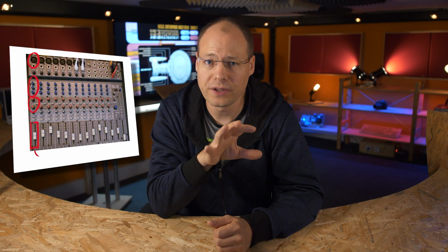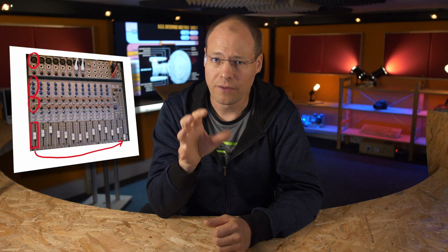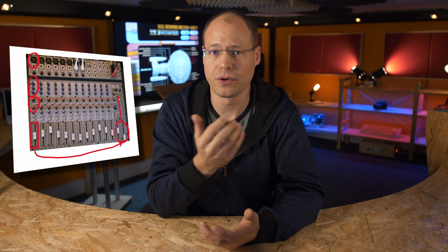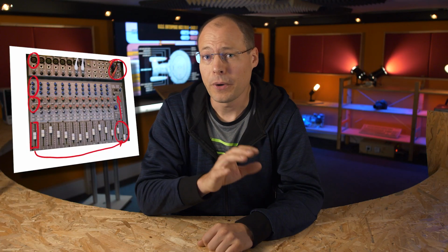Before we get started, here's a quick look at the typical signal path of an analog audio mixer. The input signal is usually fed to a preamplifier and then to a multiband equalizer. If necessary, a few aux paths can be added afterwards. At the bottom is the fader for the channel volume. From these individual channels it then goes to the main section, from which it then goes to the PA or recording or anywhere else. Modern digital mixing consoles often work on this principle as well, even though digital signal processing, or DSP, makes signal routing much easier.